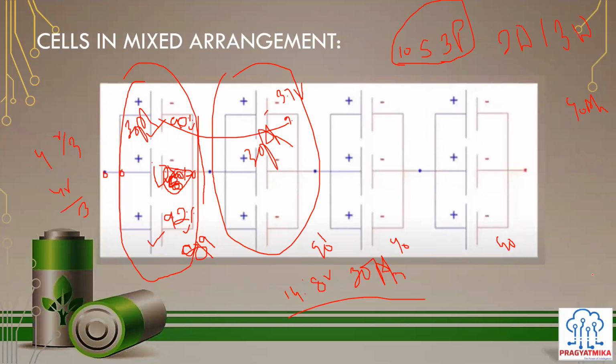It can be used, for example, if you are making a 400 volt traction battery pack. Now for this, how much would the series count be? It is in the range of more than 100. 400 divided by 3.7, how much does it come to? I think 108 or something. It is 108, right? So 108 cells will be in a series.